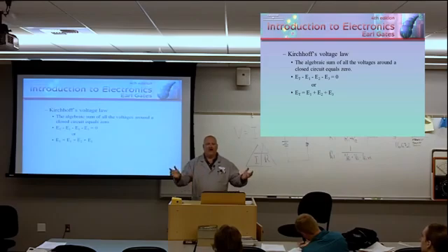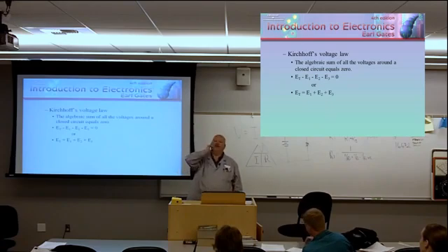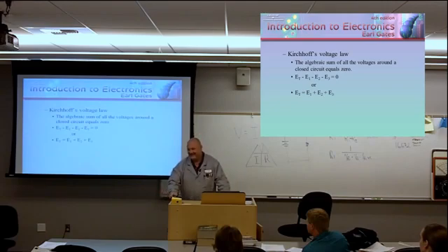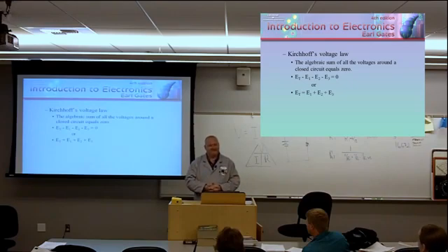Again, like my former esteemed colleague on the submarine, Mike Wyrup was his name. Wyrup, weird name. He'd be the kind of guy like, well, I think it's the wiring, Joe. I want to do continuity checks. I mean, you're talking big multi-pin connectors, and you're going to disconnect and check the continuity. It could take months. You really think a wire broke in the middle of the night behind that equipment rack? I don't think so. I think it's maybe something like the controlling device.